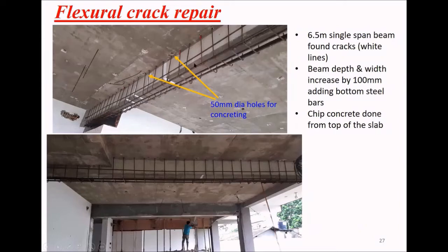Right? Then we calculate what are the requirements of this reinforcement and what are the reinforcement they provided originally. Then actually, if we provide an additional 20 millimeter bar to this existing reinforcement, these cracks will not be formed. I mean, that is insufficient reinforcement they provided. At the design stage also, we found that is the mistake done by the design engineer. So rectification is very costly.